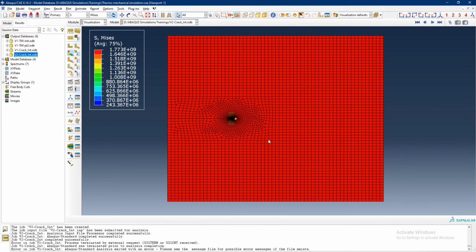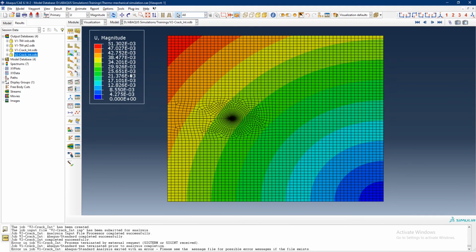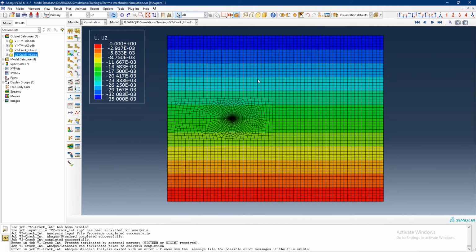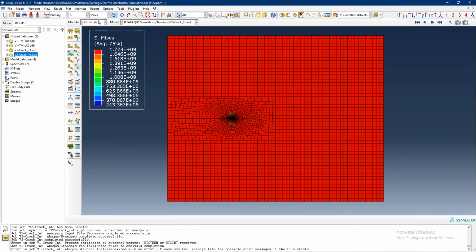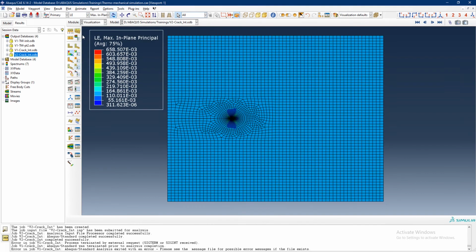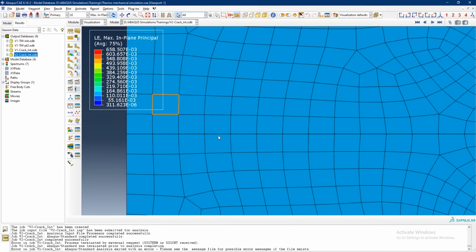And we see that we obtain similar results under compression, that there is compression in this direction, and we can see that the whole bulk is deformed, and probably there will not be any major stresses, but rather strains when we look at it, because the material is able to deform in this direction. So this is how we define the interface between these two crack faces.